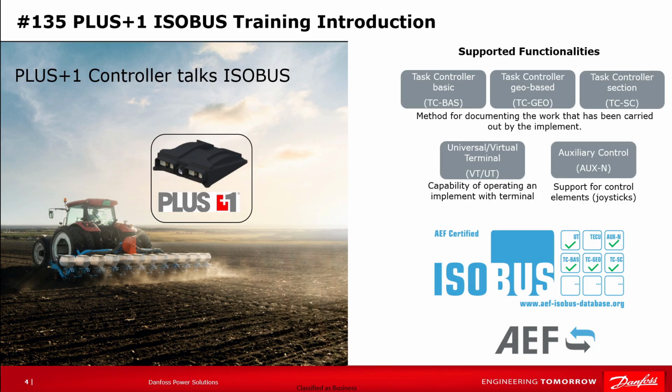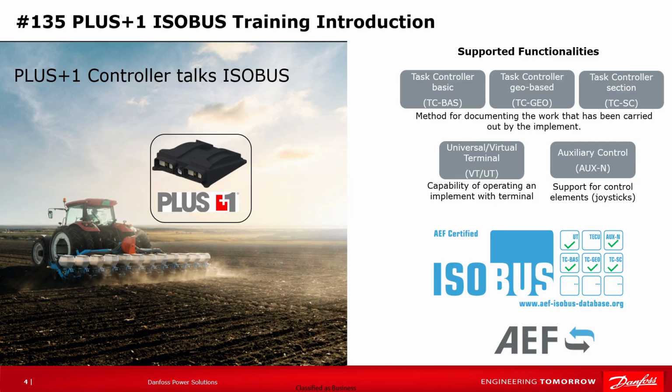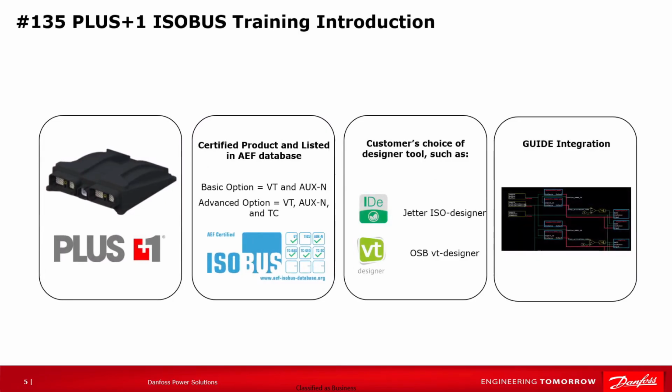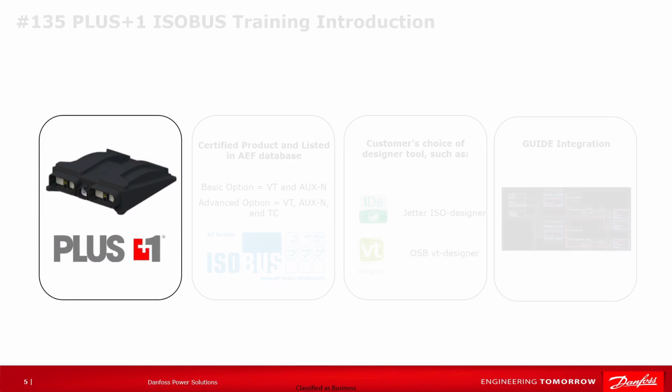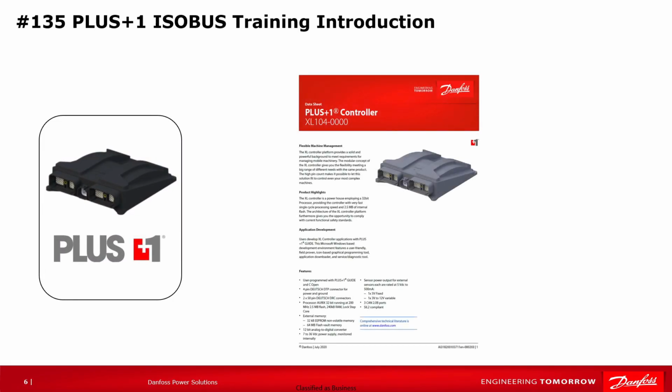For this purpose, the Danfoss XL104 controller was expanded with an ISOBUS stack, which enables standardized communication between the tractor and the implement via ISOBUS. The XL104 controller was selected as the first one to start with for ISOBUS communication, but our intention is to propagate this to other controllers in the future.